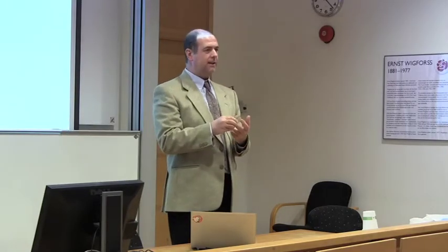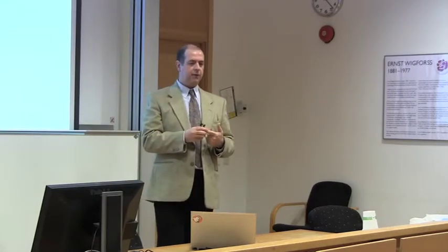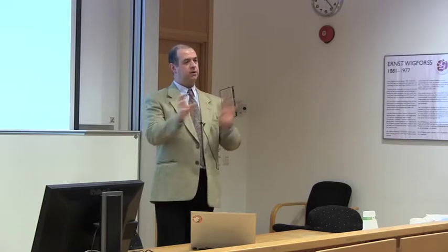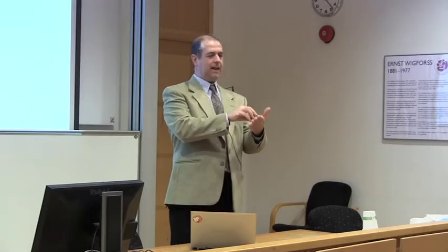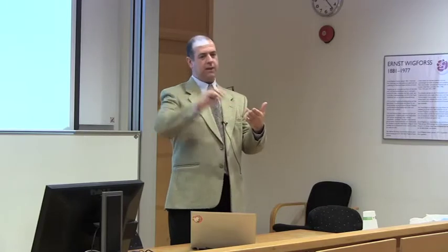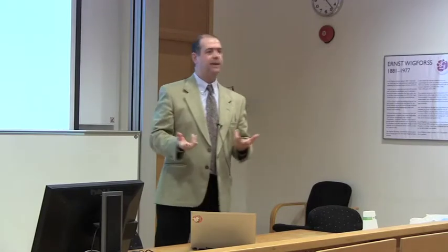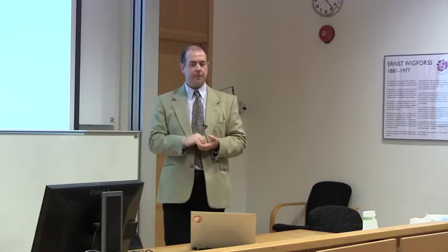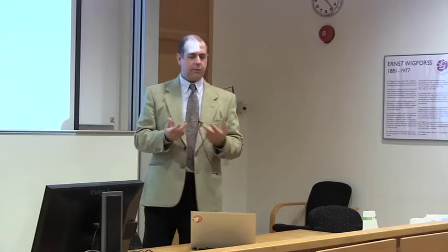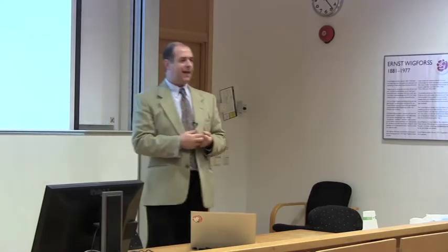But the key point is that the worst case computation times are essential, and other information that would be useful is the dependencies between portions of code. Dependencies are also important because when data is passed from one portion of code to another, it creates a data dependency that I need to also take into account in my graph. But the worst case computation times are for sure essential to perform the analysis.